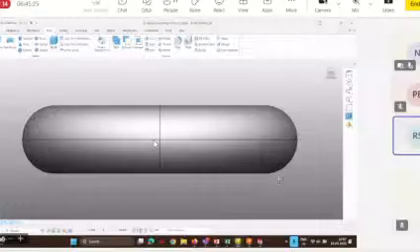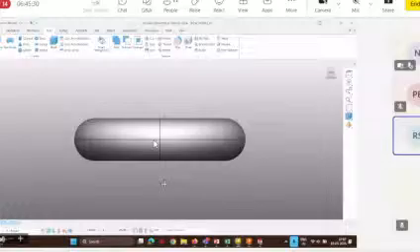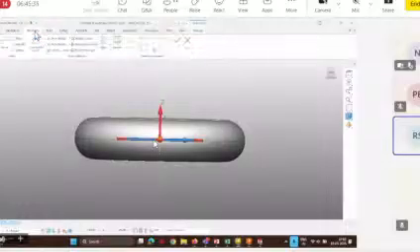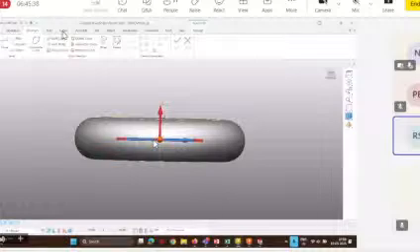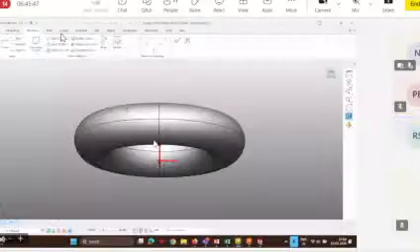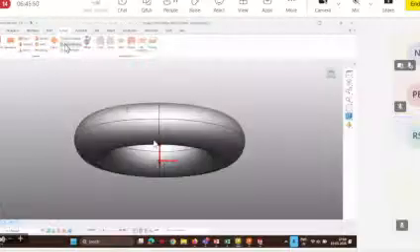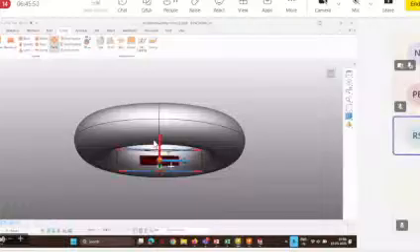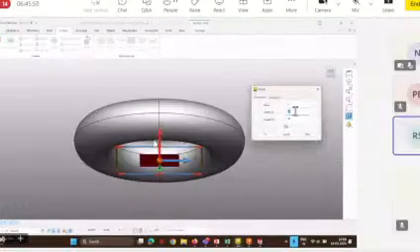To do so, we proposed one method called double slicing. Maybe I'll just go over here. Let's get one work plane, slicing plane over here. First the work plane will be created at the bottom, then we'll create one slicing plane over here. Let's define this width and breadth to be around 300 by 300.